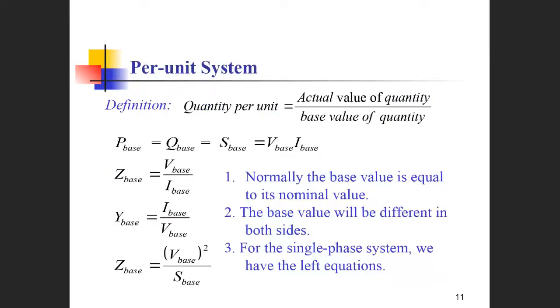A last point is the per unit system. That means we use the ratings of the transformer as the base values of the unit to describe the system. A typical usage is that we usually describe the internal impedance of the transformer as a percentage of the base values. For a given transformer, the primary has its base values and the secondary has its base values.